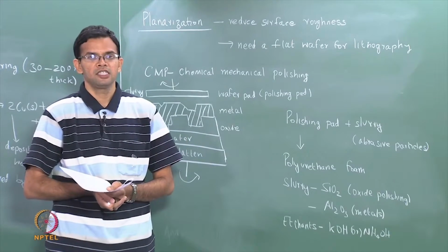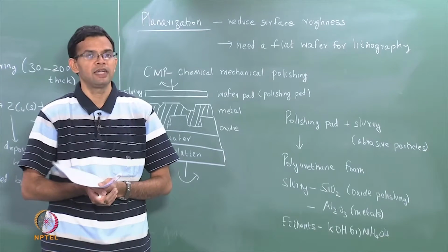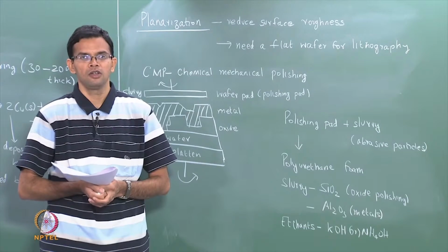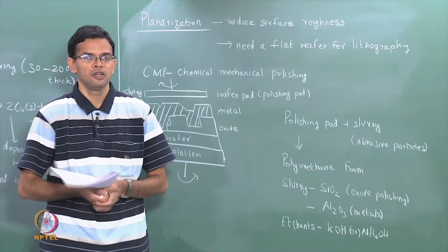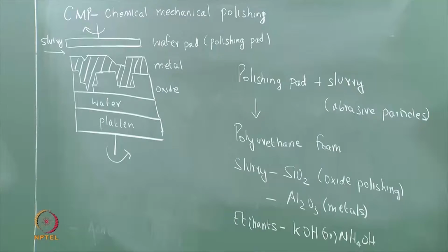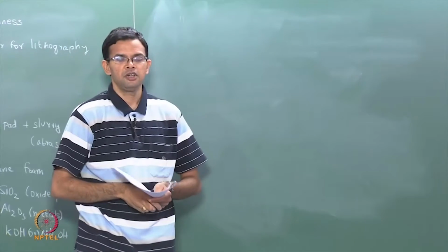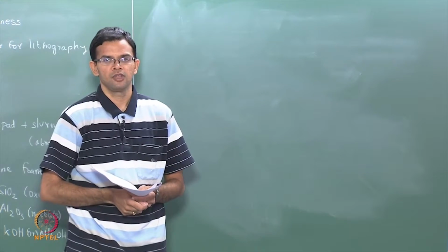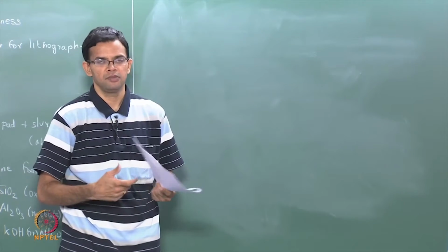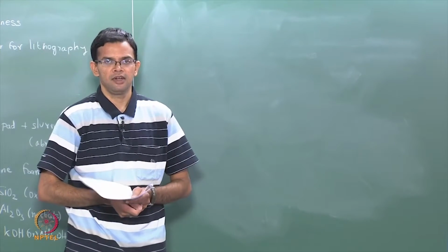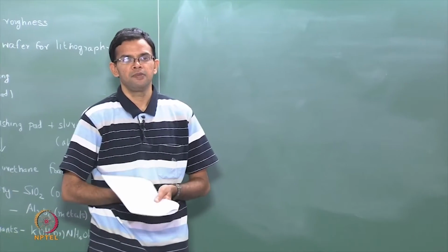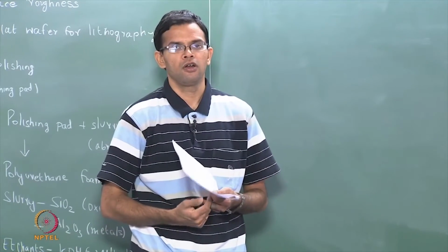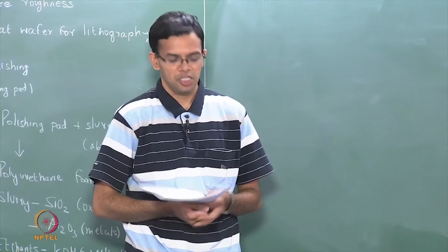So planarization is combined along with copper metallization to create the metallic layers. This process is called the dual Damascene process. Let us look at that briefly. As I mentioned earlier, copper metallization was introduced in the 1990s. It was originally introduced in IBM and then became an industry-wide standard. Copper essentially replaced the aluminum, silicon and copper alloy that was used for metallization earlier.